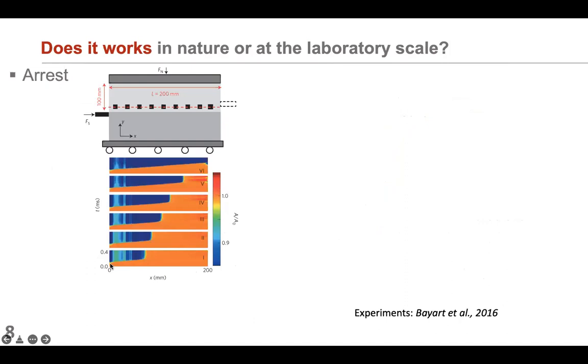Here I'm showing you the same kind of experiments, also done by the group of Jay Fineberg and by Elsa Bayart in 2016, where the authors were able to induce, at the laboratory scale along the PMMA interface, also finite ruptures. So you can see here different successive events, and in blue you can see the extension of the rupture during the successive events that occur along the interface.